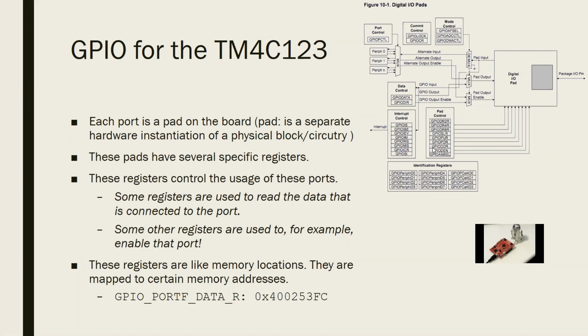You tweak them, you change their bits, and you use them for different purposes. And actually, we have gone over this. We have manipulated some of these registers so that we were able to use some pins of port F as output pins, and those pins being connected to the RGB LEDs, we were able to make color, if you remember.